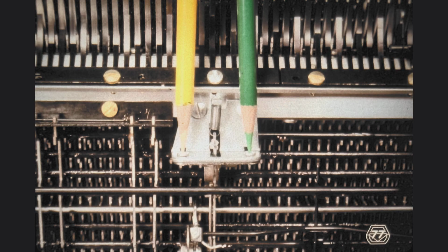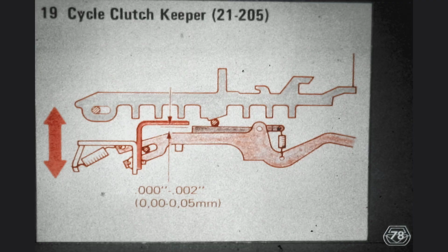From this angle, however, you can readily see whether or not the interposer latch springs are flush with the bottom edge of the interposers, and also whether or not they are centered with respect to the interposers. Be sure to check the adjustment at the center right and the center left, as well as the extreme right and extreme left because of the 2 sections of springs. Take whatever time you need to carry out this assignment.